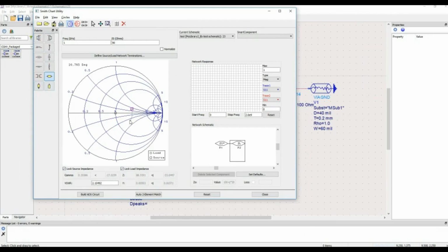These two are stubs. So once I take this transmission line, I can see, based on the electrical length of the transmission line, which you can see here. So here it is 0, I am at the same point near 0. Now I am increasing the degrees and likewise I am moving on the Smith chart. So I can either drop this point here or I can have a transmission line length till this. So for example, keeping it minimum electrical length transmission line, I select to go up to this point.